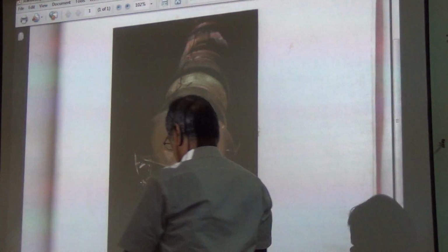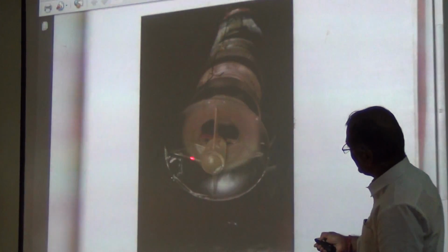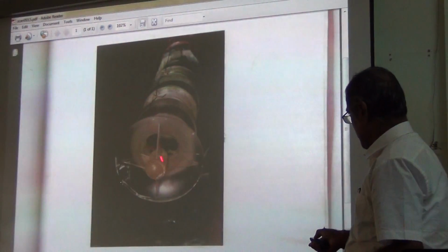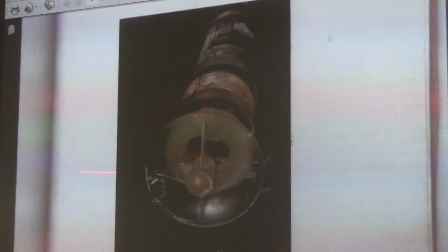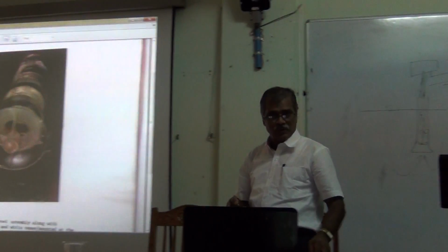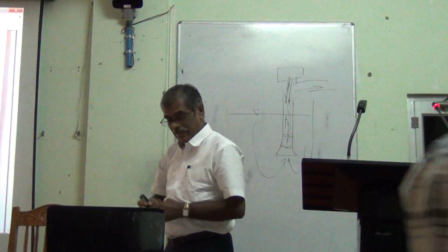These are static vanes. You can see the vanes. They are static. These are not the impeller vanes. These are not the pump vanes. Static vanes at the inlet. This is to break the circulation. You don't allow vortex. So if you have intermediate static plates, then the vortex will be broken. Is that clear? Vortex breaker. You don't want vortex. The swirling velocity would induce air suction.